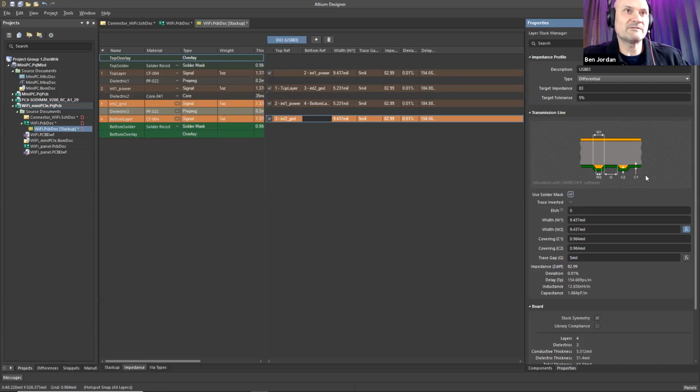You need to specify that in two places because mask is spray painted onto the board and then hardened with UV light. So it's typically thinner over the traces than it is over the bare board surface. So if you want to specify the covering thickness, you can do that. You'll need to talk to your fabricator and get them to give you a sample or cross-section data about their process to know exactly what those thicknesses are.